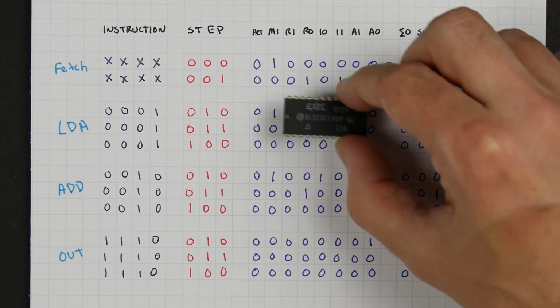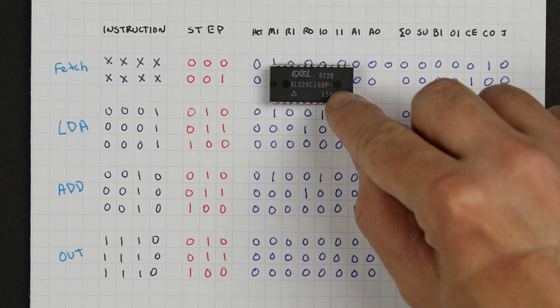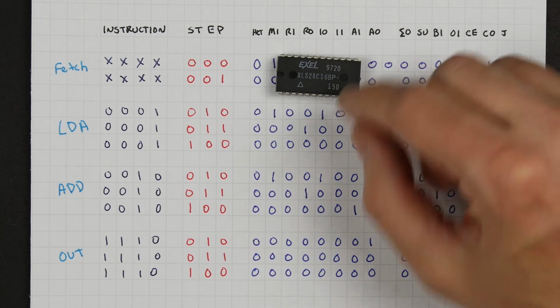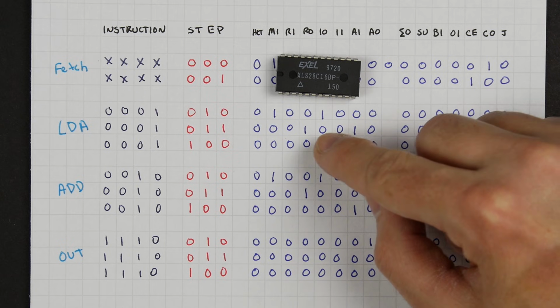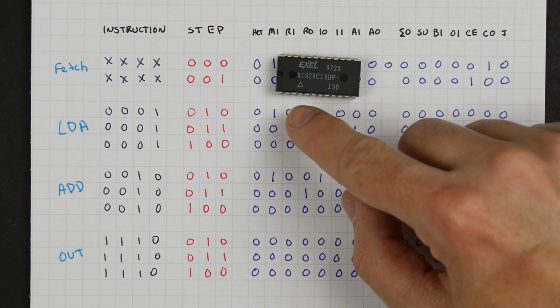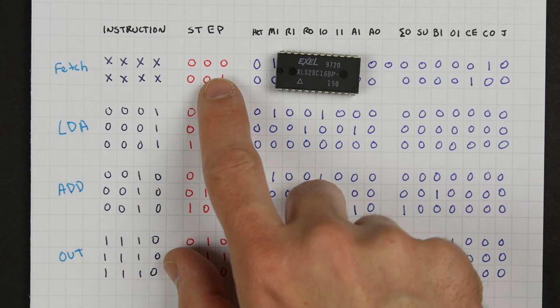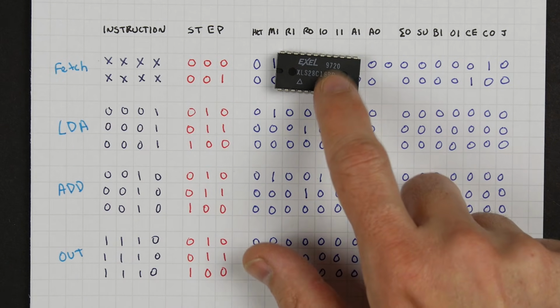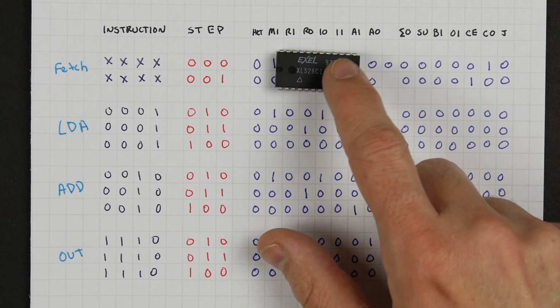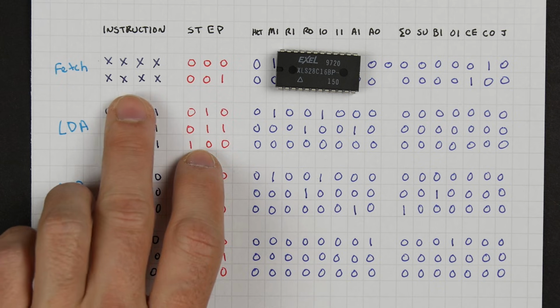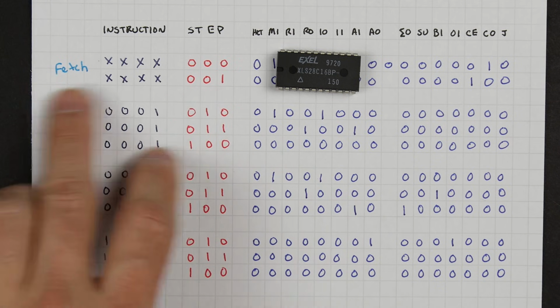The problem, of course, is that the EEPROMs that we've been using are these 28C16 EEPROMs, and I'm going to continue to use those for the control logic as well. But you'll remember, they've got 11 address lines going in here, and of course we only need 7. And there's only 8 data pins, so there's only sort of 8 outputs. And so as far as the address lines go, that's easy enough. We can just set the rest of them to zeros.